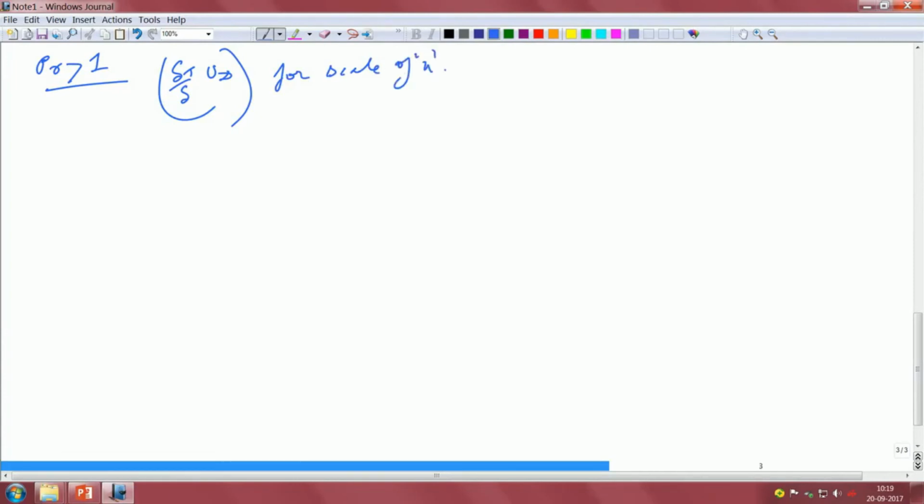However, the basic assumption in that case was that delta is much greater than delta t. That was the assumption in a flat plate boundary layer. So, this scaling was valid, but here it basically spreads over the whole diameter of the pipe. So, this scaling is not correct over here.